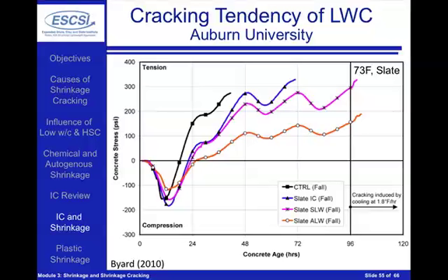What we can see here is they were going through a case where they were essentially starting to talk about what happens when you are casting a bridge deck and when you're having the daily thermal cycles for a fall type of construction environment. And here what you can see is the plain concrete shown in black, the internally cured concrete shown in the bluish color. What you can notice here is a later date of cracking inside of the system. The main reason here is because you're reducing some of the stresses that are developing in the system.